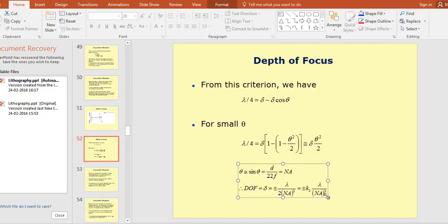Again, there is a practical constraint in using bigger lenses. So the best alternative to get the better resolution is either you decrease the wavelengths or you do the same lithography using some higher refractive index material, like we do in immersion lithography using water instead of air.